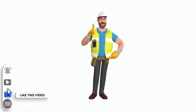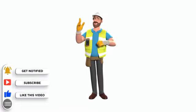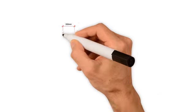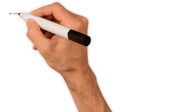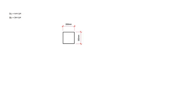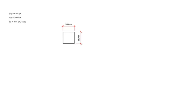In today's video, we will demonstrate how to determine the dimensions and reinforcement of a pad foundation using a worked example. A 350 mm square concrete column supports a dead load of 400 kN and an imposed load of 300 kN, assuming a permissible bearing pressure of 100 kN per square meter. How can we find suitable pad foundation dimensions?